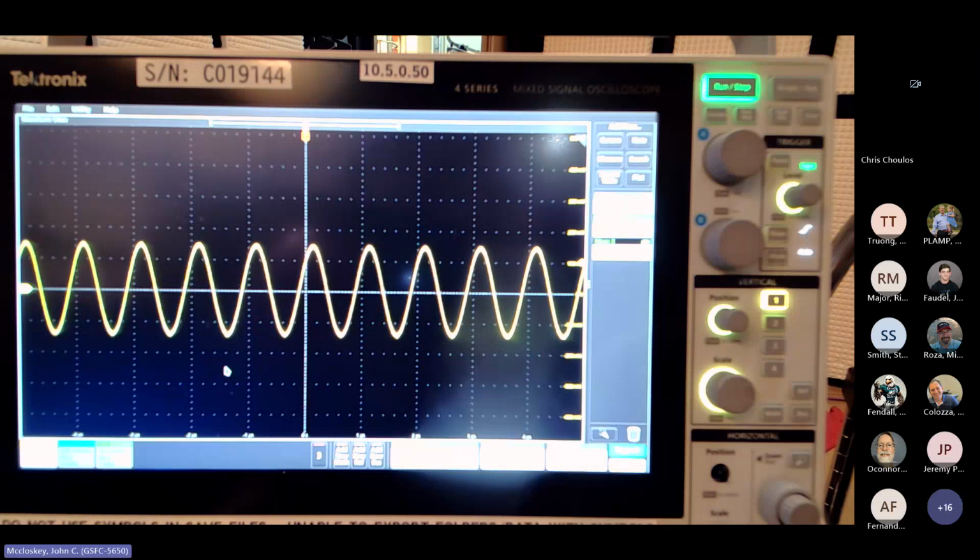But when you have anything other than 50 ohms out there, which is most of what we're dealing with in CS114, you have to expand your model to realize that it's double this potential going through a 50 ohm source impedance. Is everybody clear on this? This is absolutely crucial for everything that comes next.